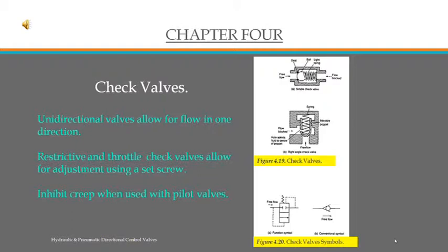These are very useful in hydraulic pneumatic systems when left idle for an extended period of time because they allow the cylinder to maintain its position. When they do not maintain position, it is what is known as creep.